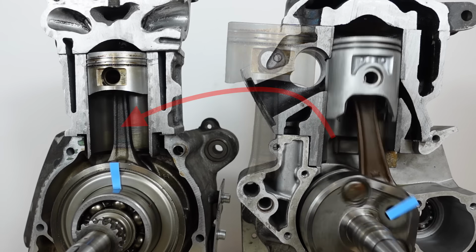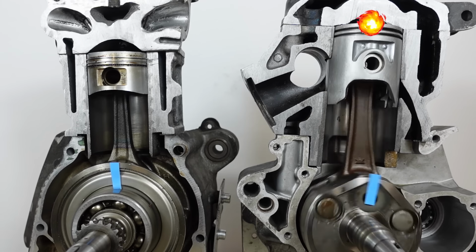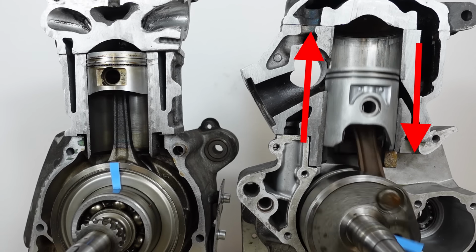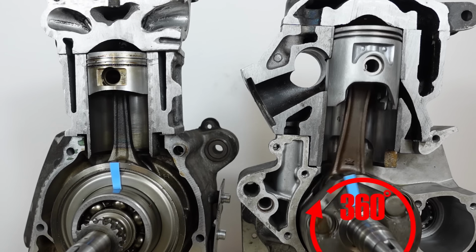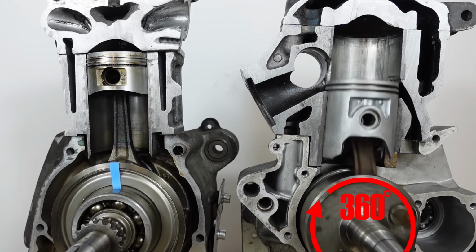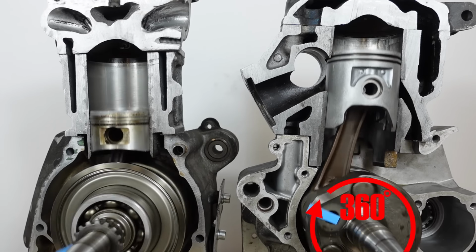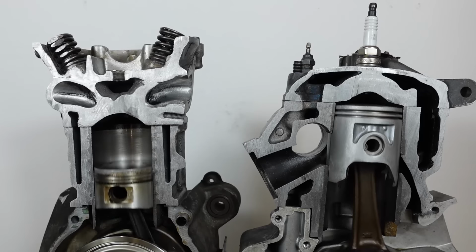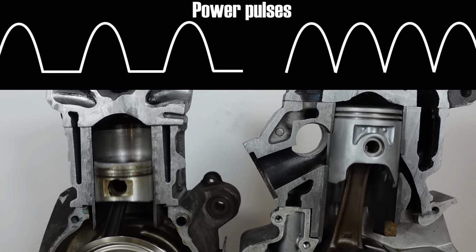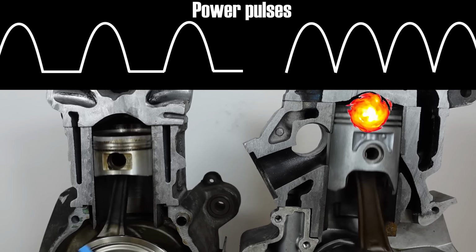As you can see, each time the piston is at top dead center, a combustion event occurs. This also explains the name two-stroke. The engine only needs 2 piston strokes to complete its combustion cycle. In other words, each 360 degrees or 1 full engine revolution results in a combustion event. Whereas in a four-stroke engine, combustion occurs only every other time the piston reaches top dead center. Combustion occurs only every 720 degrees of engine rotation. This means that the two-stroke produces twice as many combustion events or power pulses for the same RPM, which means that, at least in theory, the two-stroke engine can make twice as much power for the same displacement compared to a four-stroke engine.